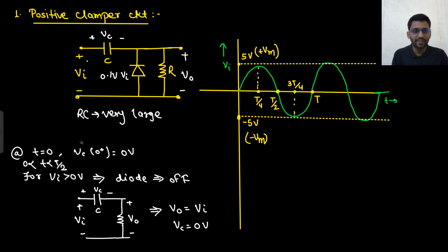And when we study the peak detector circuit, we will see that it will be somewhat like this. In a peak detector, the output is connected to the capacitor. The output is parallel to the capacitor. So in a peak detector circuit, you can also directly see the circuit. This is just a way to remember that if the arrow is upward, it is a positive clamper. Arrow is downward, that means it will shift the waveform downward. Or you can analyze the circuit as well, but we will not waste much time in the examination if the standard circuit comes. If there is a standard circuit, we will quickly solve the problem.